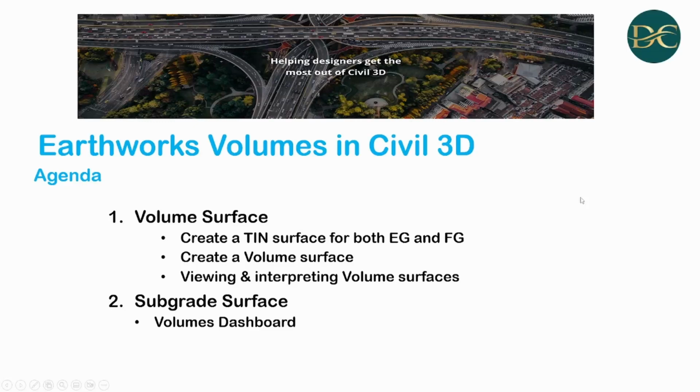Welcome to today's session, which is about how to create a parking layout of a retail site. In this video, we'll focus on doing volume calculations for our parking design. So for this session, we will create a TIN surface for both our EG and our finished design. We will then create a volume surface, and then we will view and interpret our volume surfaces. Thereafter, we will look at a subgrade surface, and we will be using our volume dashboard for that purpose.